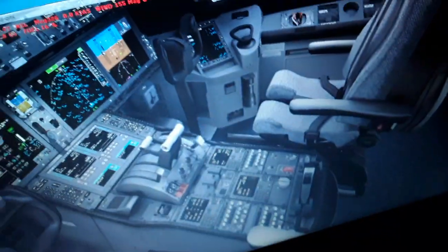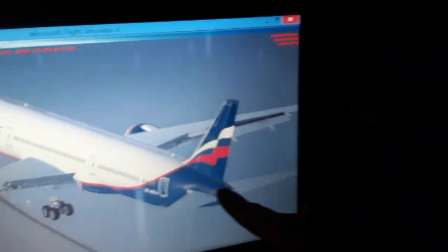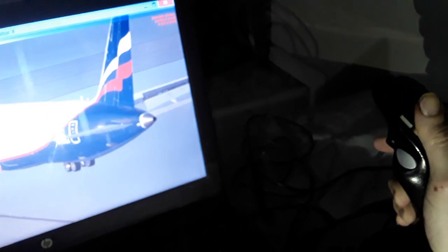You can see we have also, as I told you, the horizontal trim stabilizer. So this section trims the horizontal tail of the elevator as we are flying. We use the elevator here for climb and descent. We have the elevator trim also to balance the aircraft in flight. So you can see the horizontal tail movement.